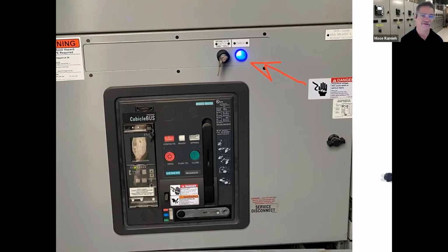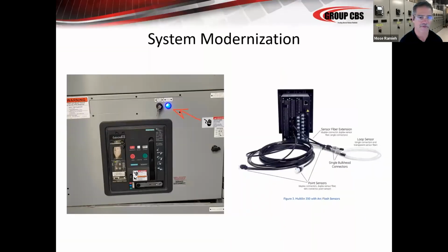But I also want to stress that these are great, but you've got to make sure that when you're done, you put it back into the normal mode, right? So that the settings go back to their higher settings. In normal system operation, we're trying to balance safety and reliability. In maintenance mode, we're preferring safety. So we've got to make sure that after we're done, we flip it back so we achieve that balanced system between safety and reliability. So remember to put your maintenance mode switches back in normal mode when you're done.